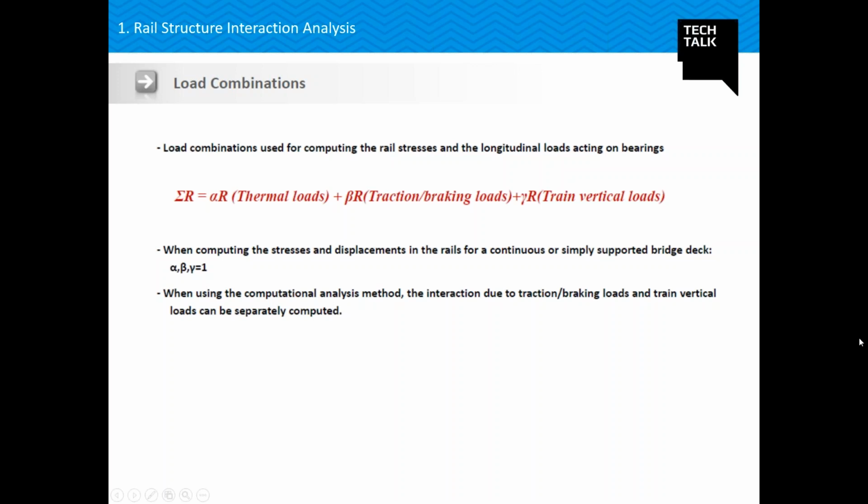Now, my analysis being non-linear, I cannot combine my stresses by linear superimposition as shown here. I cannot superimpose the results from a non-linear analysis linearly.